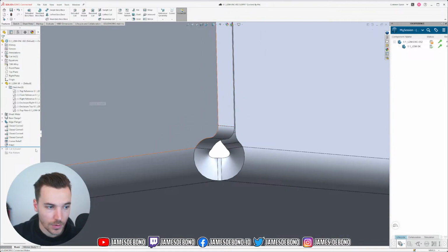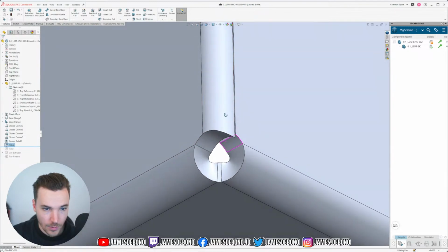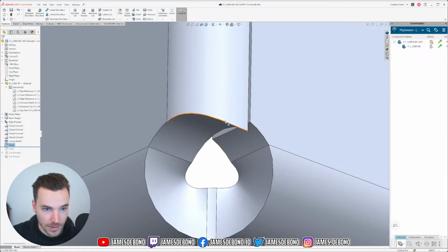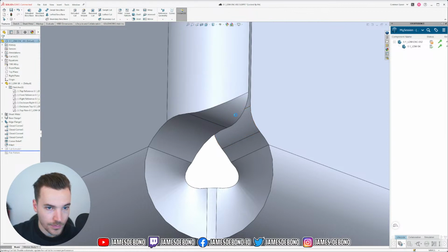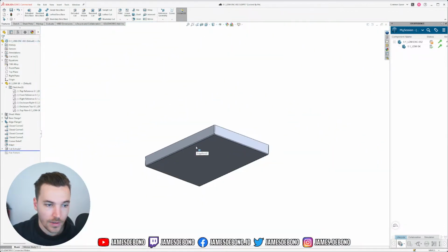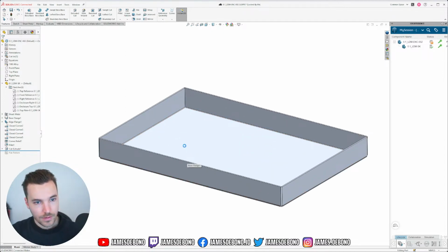So I could also put it before this fillet, but then it should be 2 millimeter radius, but then I can't fillet this edge because this is also this edge, so then this one's not going to know what to do, and you can see that it's erroring out there, so it's better to just do a cut. Okay, so that's the bottom of the enclosure.